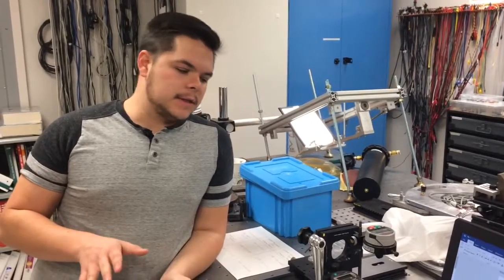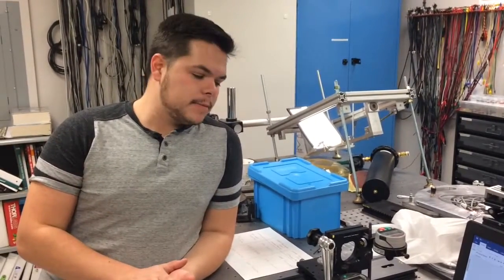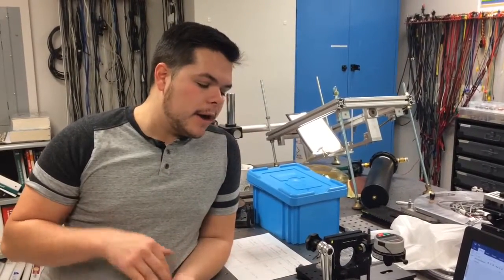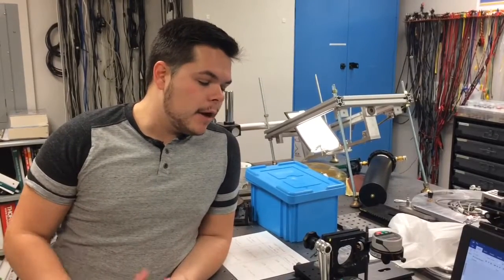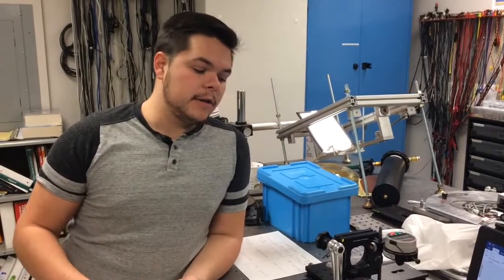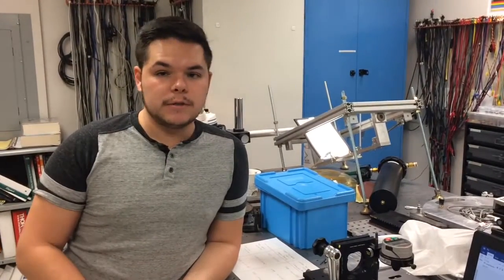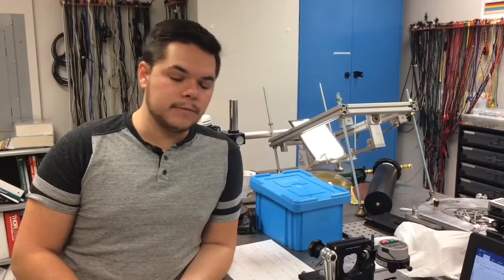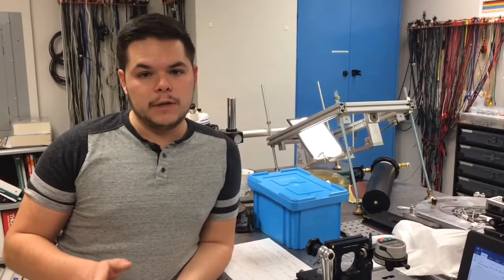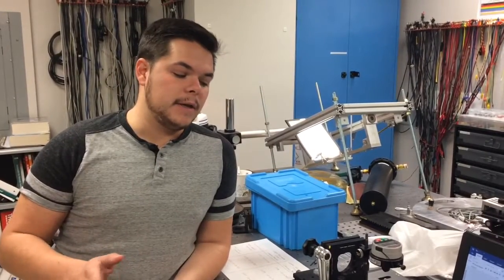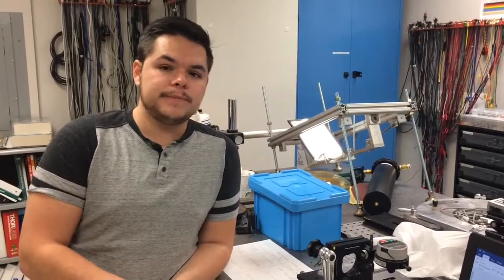Putting all other errors aside, the error that we're actually testing in this experiment is the error in the kinematic interface of the mount. So any manufacturing error that could have happened, whether it be the balls not being perfect spheres and not having point contacts with their interfaces, any error in the shape of the cone, the shape of the groove, anything like that, errors in dimensions and material properties, all of that goes into the errors in the kinematic interfaces, and that affects the repeatability, making it impossible to be zero.